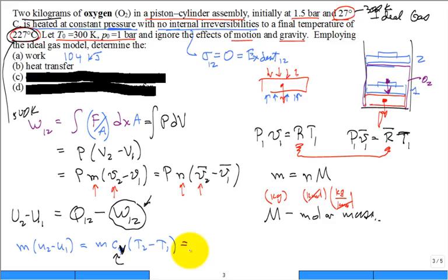You can. But you get U bar 2 minus U bar 1. That U bar 2 is evaluated at what temperature? 500 Kelvin. And this U bar 1 at 300 Kelvin. Do you see that in table A22? U bars instead of U without the bar. Look at the header in the table.